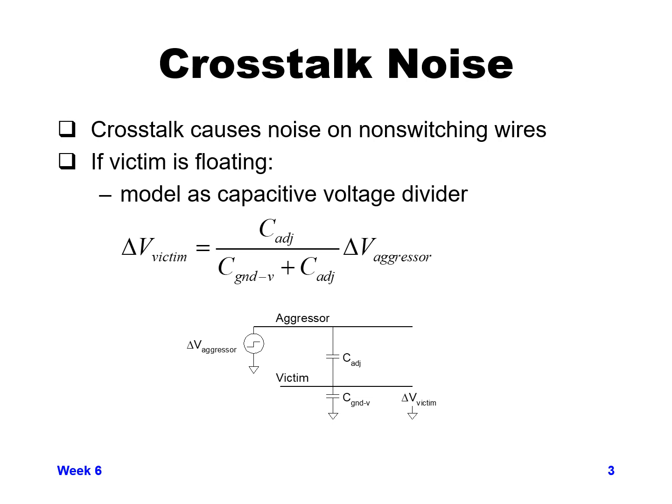So one possible way that your wire is not switching is if the victim wire is floating. The terminology used here is that the wire that's switching is called the aggressor wire or the attacker, and the wire that's not switching is called the victim wire. If the victim wire is floating, so it doesn't have any active driver on it, that just means the victim only has capacitance on it. And so in this case, you can model the victim wire as a capacitive voltage divider.